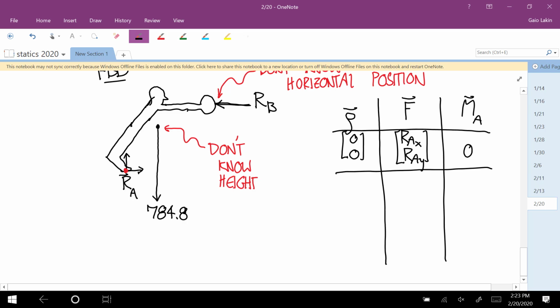And now I'll go to the weight force. The horizontal component of the row vector is positive 0.5. The vertical component we don't know, but it's not going to matter because this is the line of action. So I'm just going to put that in as 0.